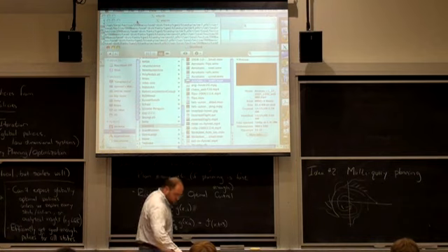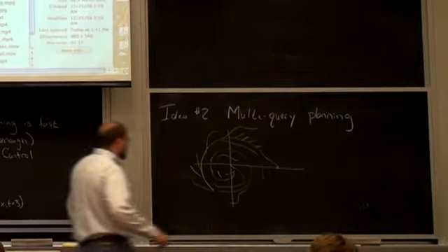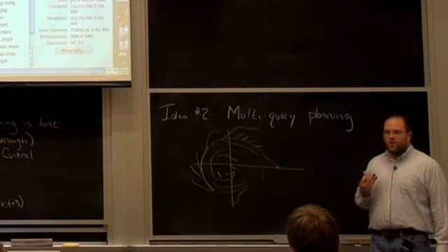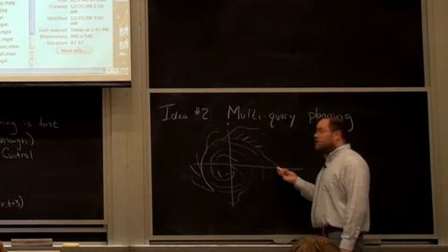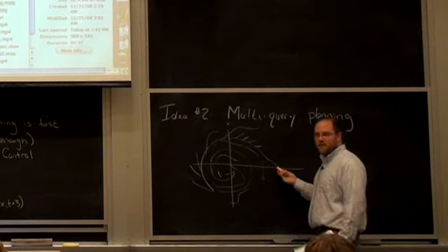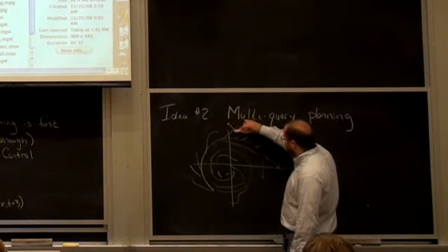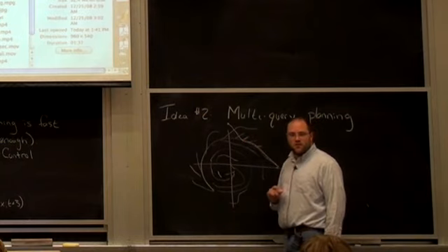It happens that one of them got me from the start to the goal in my initial problem formulation. But instead of throwing all that computation out and just keeping the nominal trajectory, I might as well store it. If I get a new problem, which is, let's say I wanted to start from here and get to the goal, then really all I need to do in my new planning problem is connect back to my old solution, right? If I can find a new plan that gets me back here, then I can just ride the rest of the solution into the goal, right?